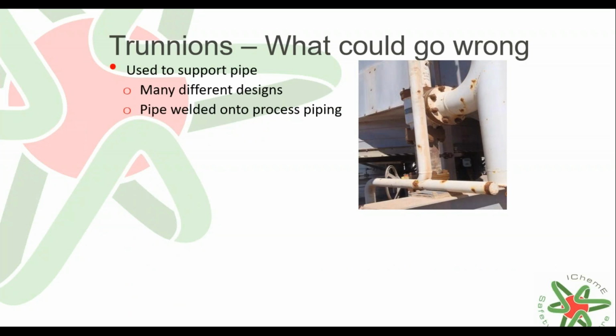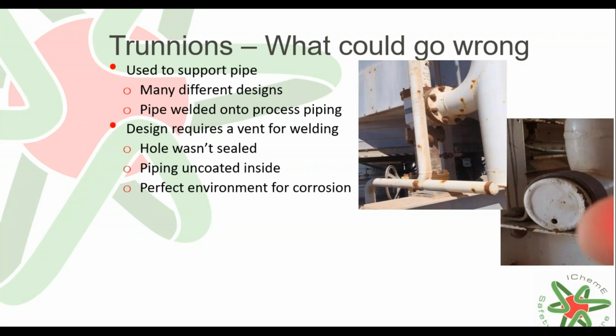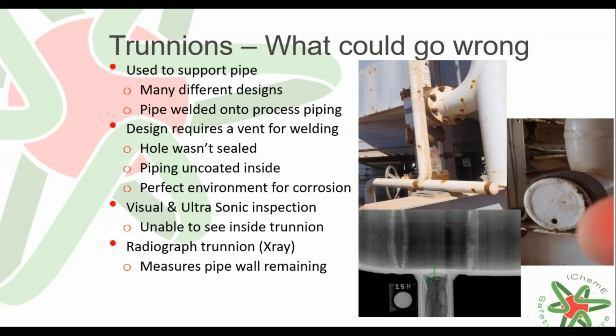So as we go on to a particular piece of piping design, which puts all that into question, is a thing called trunnions. Trunnions come in many different shapes and sizes, and there are advantages and disadvantages to all of them. This one in particular is looking at what we call pipe trunnions. A pipe trunnion essentially is a piece of structural pipe, which is exactly the same as the pressure containing pipe, but it's welded onto the pipe to provide a support.